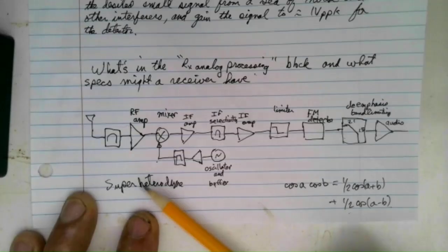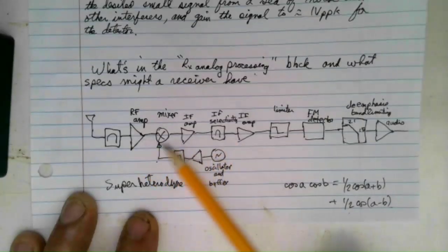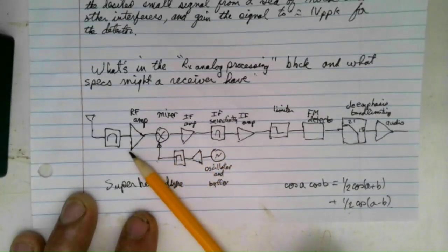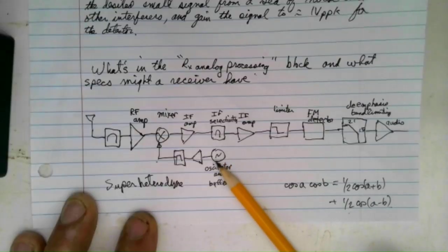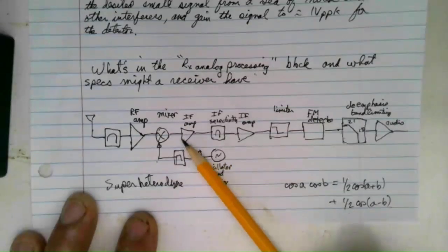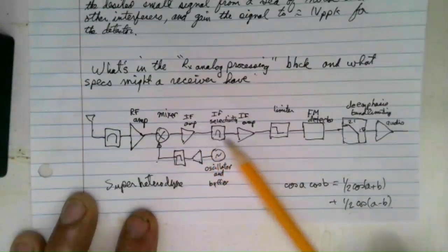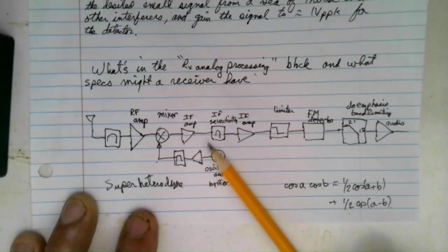And the superheterodyne was a giant leap forward. Even digital receivers have this superheterodyne concept. So we shift the whole band down, and then you adjust this oscillator frequency such that your desired radio station lands on this filter, and then the rest of the band gets filtered off.